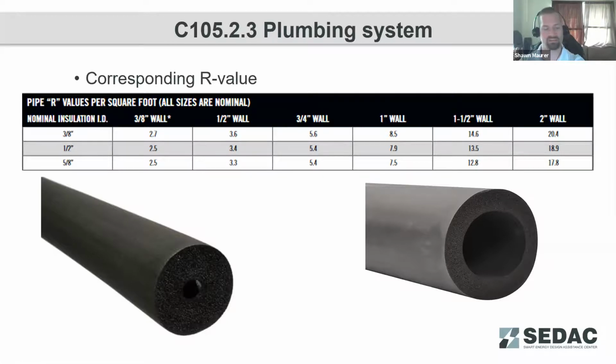Now that more and more systems are moving towards high efficiency enclosed combustion, that's also less of an issue than when we had open combustion flues on water heaters that could backdraft and cause that insulation to melt. But important to fully insulate all the way down the piping, all the way up to the tanks where the tank is insulated. So you've got that continuous insulation throughout that system.